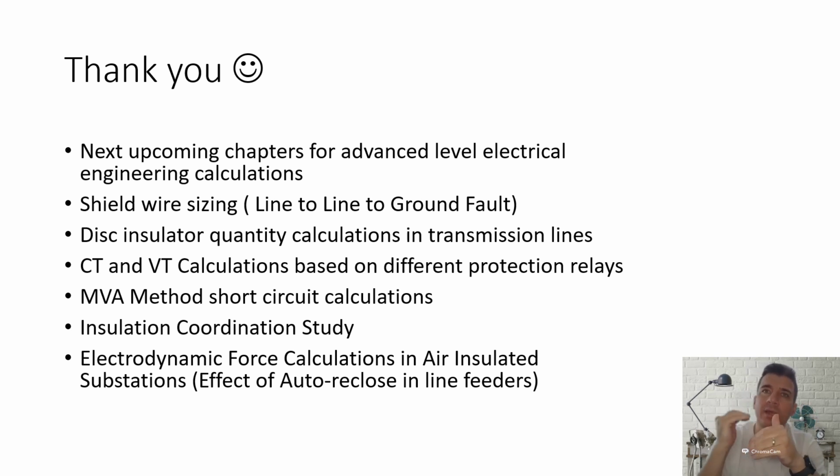Then it will provide us a very good protection for dynamic cases, for short circuits, and you will see most of them. And why don't we use auto reclose in the power generation side, generation feeders? Because of the synchronization issue, of course we cannot use that one. Hopefully in the following weeks and months, one by one, chapter by chapter, I will try to explain all these things, and maybe one more: sag and tension calculations.